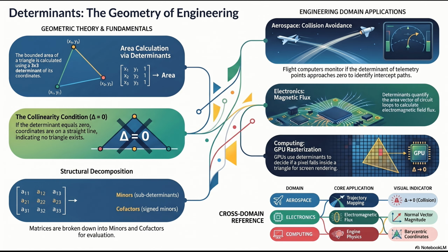They map the entire outer body of that aircraft as a mesh of thousands and thousands of tiny, completely flat, invisible triangles. And the reason they rely specifically on triangles for finite element analysis, or FEA, is that a triangle is the simplest possible polygon. Right. By definition, any 3 points in space will always create a perfectly flat plane. Yeah. You literally cannot bend a triangle without adding a fourth point. Oh, that makes total sense.